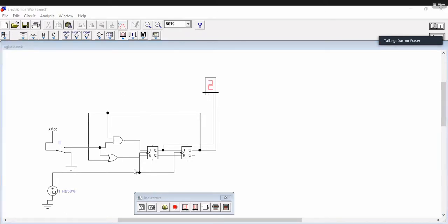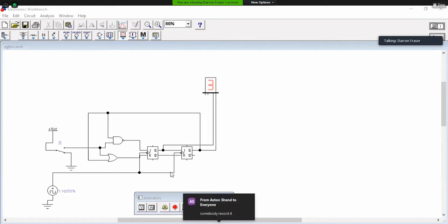The other thing about it is that a circuit like this is relatively cheap. Two flip-flops, a NAND gate and an OR gate. Well, we could convert this to one chip by building the OR using a NAND gate. So it would be one chip and another chip. So two chips and we'd be good to go.